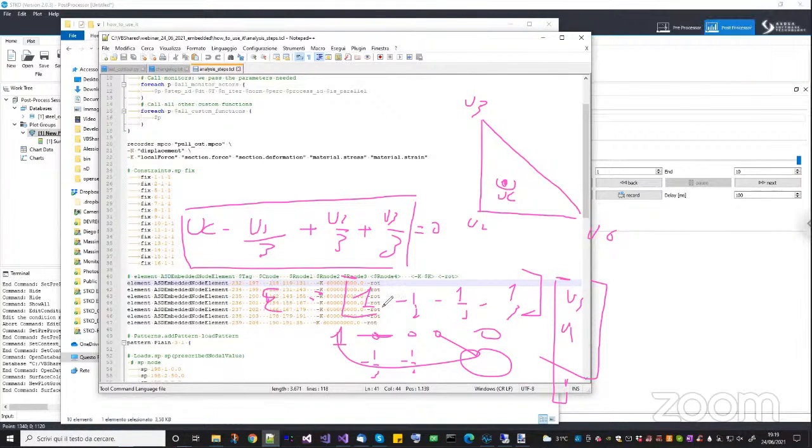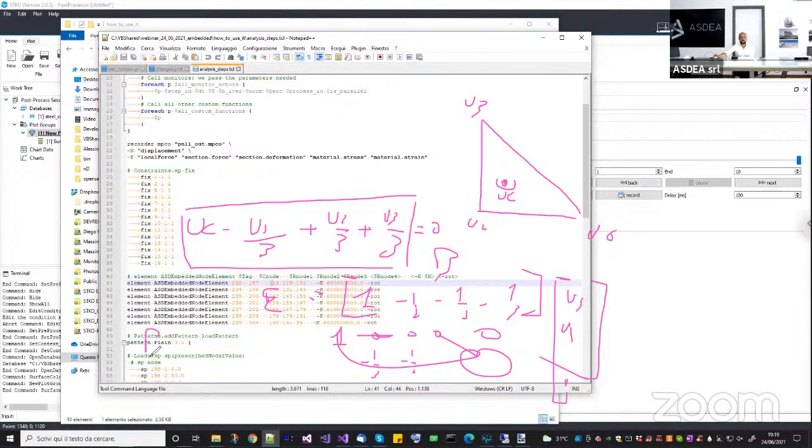Okay, I get it now. Yes. So this one is my B matrix, and my stiffness matrix is B transpose times K times B. In this case, K is the penalty parameter. So this one is constant. Like any other finite element, any kind of element can be formulated in the same way. The only difference is that now, instead of having a physical stiffness, you have a penalty.